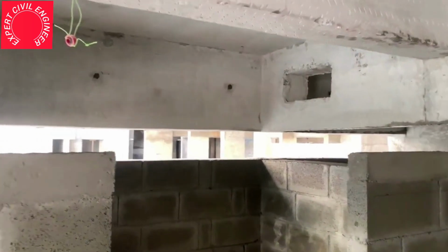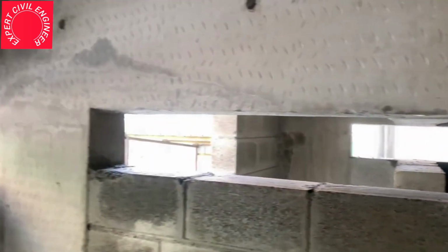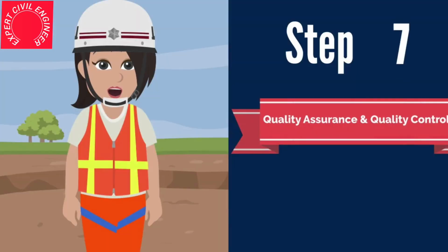Do not place the topmost block under the beam until the immediate upper floor blockwork is raised up to the beam bottom, less 1 course. It is important to ensure quality assurance while the activity is performed. Let us check what are the important points to be keenly noted.